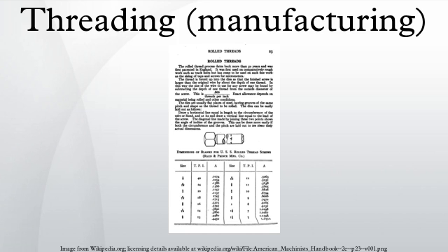Additionally, for large, awkward workpieces, it is simply easier to let the workpiece sit stationary on a table while all needed machining operations are performed on it with rotating tools, as opposed to rigging it up for rotation around the axis of each set of threads. There are various types of thread milling, including several variants of form milling and a combination of drilling and threading with one cutter, called thrilling.